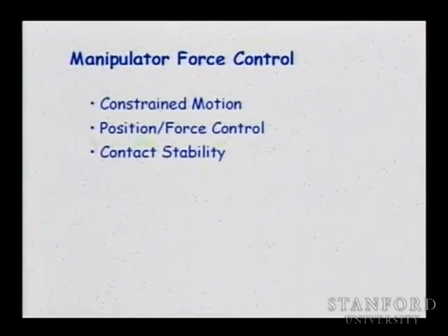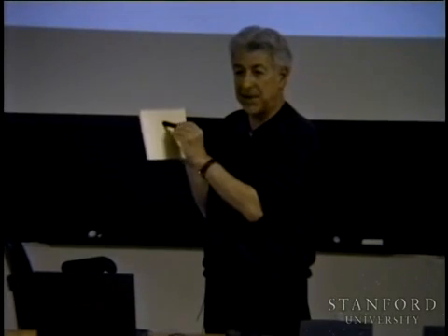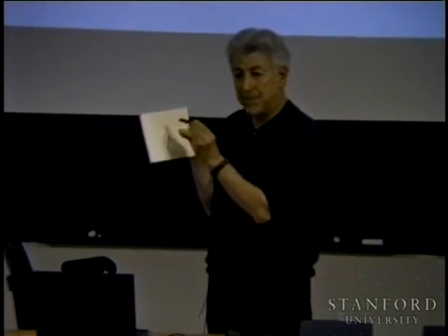Finally, we need to deal with the problem of controlling contact. So moving in free space is one thing, but when we are going to move in contact space, it's a different thing. Applying this force puts the whole structure under a constraint, and you have to account for these constraints and compute the normals, so as to find the reaction forces in order to control the forces being applied to the environment.